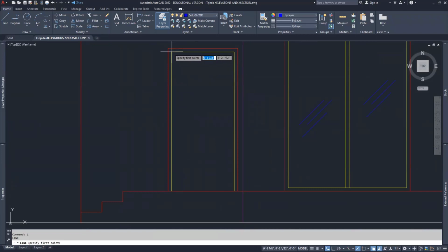And I draw a line from this endpoint, and I'm just now realizing my O snaps are off. So I will turn them back on. And I'll take it from the endpoint over to the midpoint, and then here, and then enter. I refer to this as my pivot point, also the hinge point. So it's indicating in the elevation that this is the side of the door where the hinge is located. And then where the other 2 points happen to be, that's the point that opens.